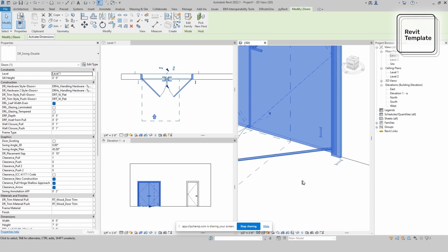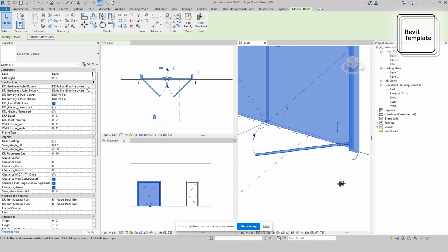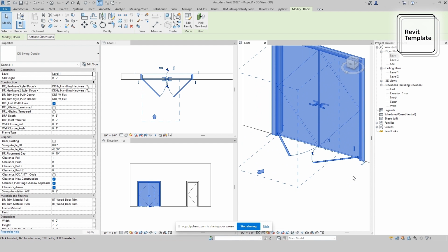This is to allow users who model floor finishes separately from the finish slab to remain visible in those views without being hidden in 2D or 3D. Users can easily adjust the settings as they see fit. By default, the settings are set to 2 inches.